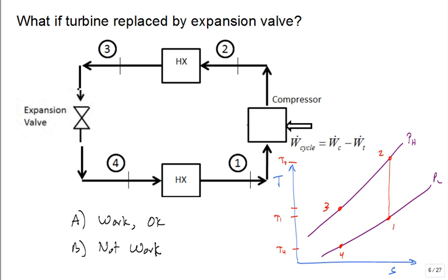See that? All right. Now, we said that if we have some isentropic efficiency for that turbine, it will kick out state 4 here. Maybe that was 95% isentropic efficiency. Maybe it's 90% isentropic efficiency. Maybe it's 50% isentropic efficiency. Well, just keep playing the game, right? Where are you going to walk state 4 out to?